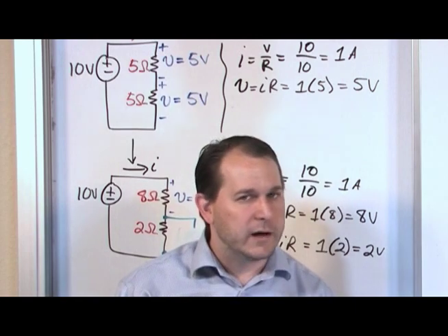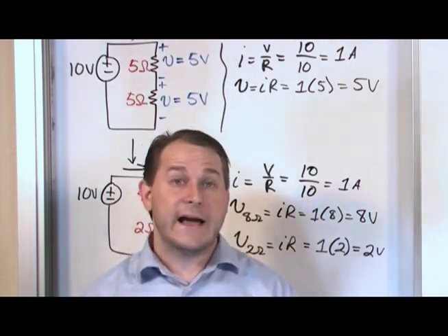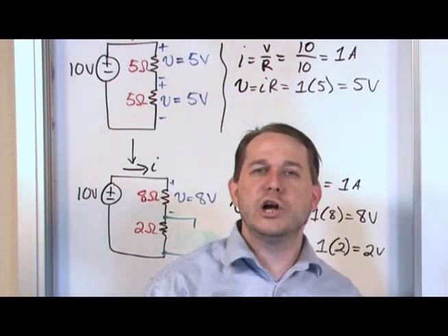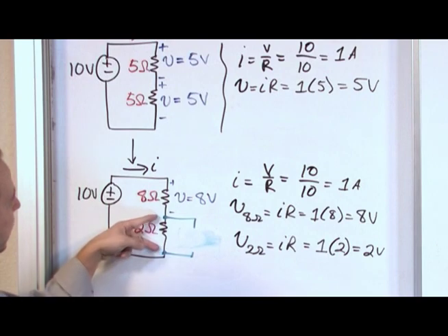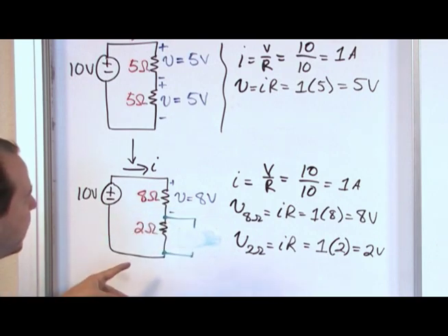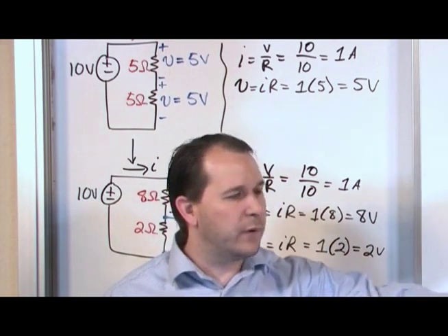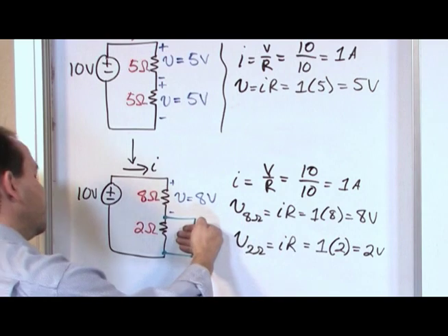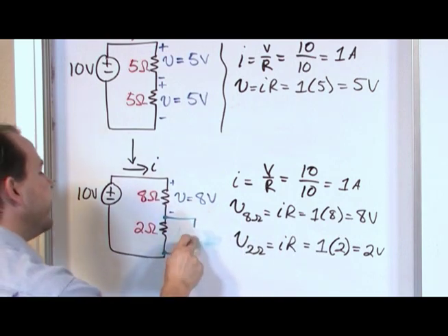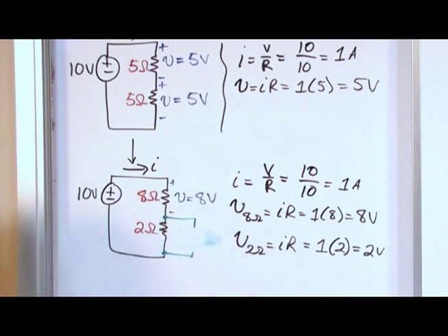Let me say that one more time. A lot of times in circuits, when you're talking about voltage dividers, they'll ask you to calculate the no-load voltage. When they say that, they mean they want you to calculate the voltage across the terminals that we're interested in, but with no load connected there. That's a perfect 2 volts delivered there, right? Now, if I connect a load, depending on the resistance value of my load, I'm going to actually change the circuit, and I'm not going to have really 2 volts delivered right across that guy again, because I'm really changing the resistor network.